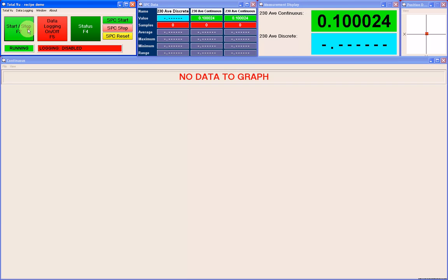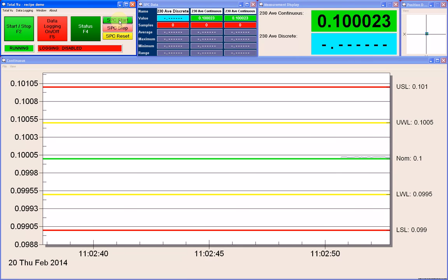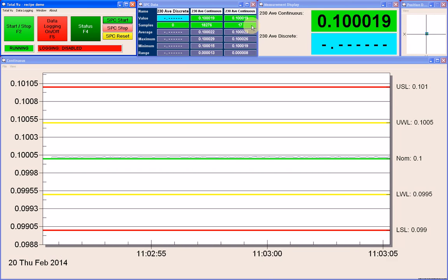With measurements running, execute the SPC Start action to start collecting data within your SPC plans according to their respective sampling rules. Notice how the sample count color changed from red to green when I executed the SPC Start action. Discontinue plan sampling by executing the SPC Stop action. Reset with the SPC Reset action. Notice how the sample count goes to 0 when reset.